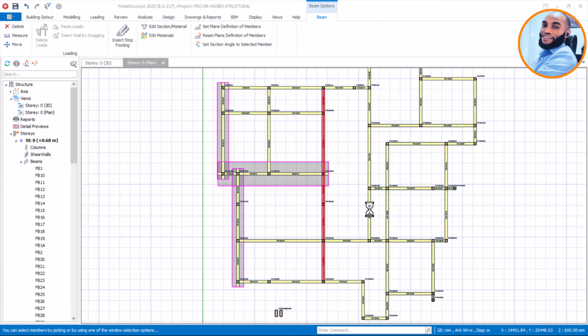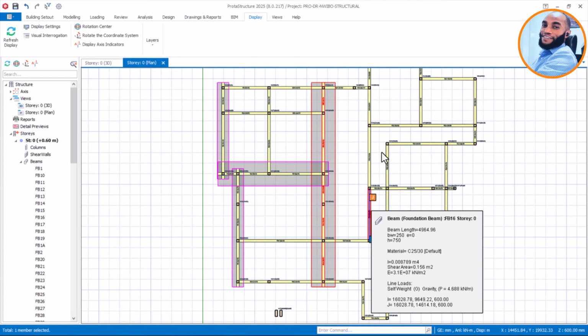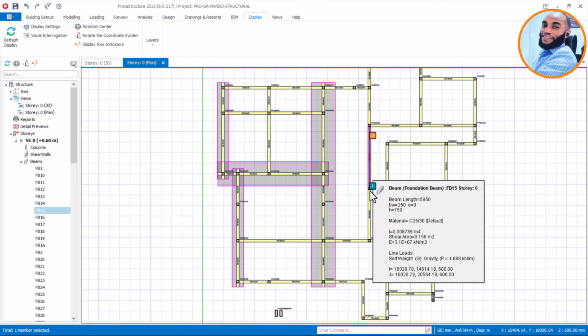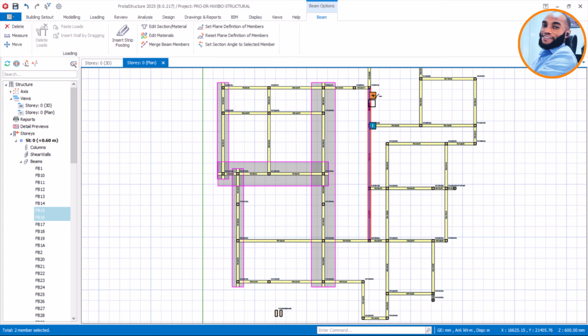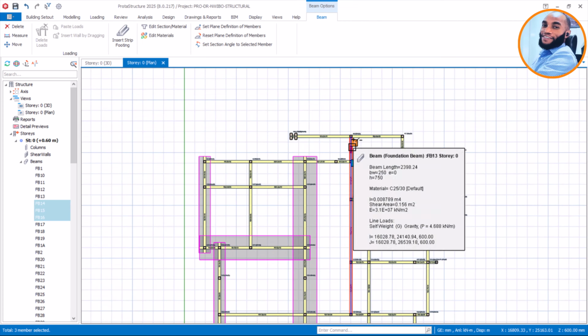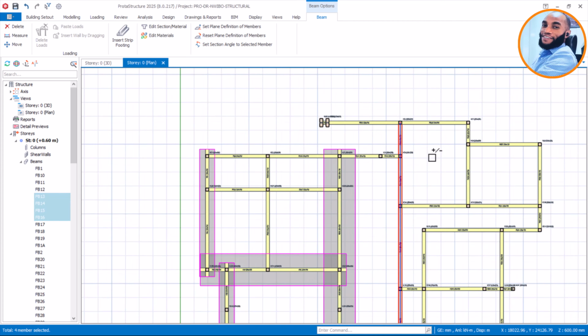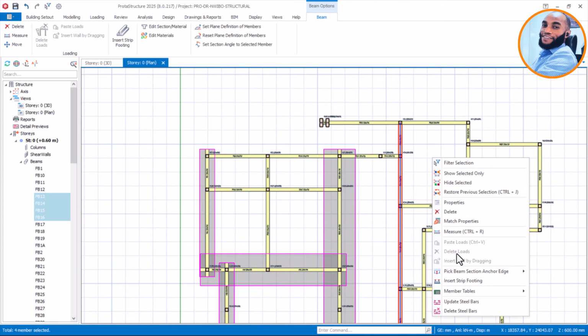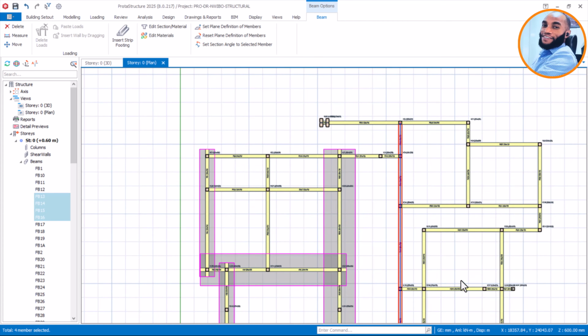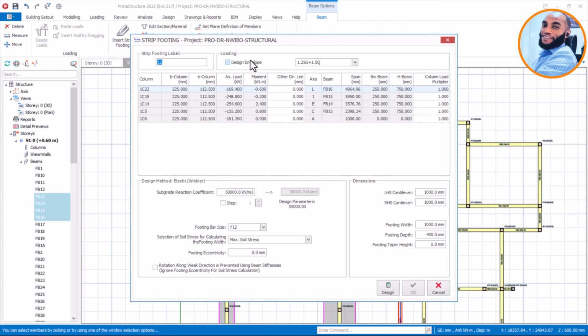Okay, that is fine. And I will come to this other one now, click on this one, then click here, and then click here. Now when it is getting bigger, there's a point where the strip footing gets bigger, you will have to move to a beam raft foundation. And when that point is reached, I will let you know, because there's some size you will see for your strip footing. You will have to change the foundation type to a higher level of foundation, which is a beam raft. Okay, that is fine. So you have 250 here, that is fine.